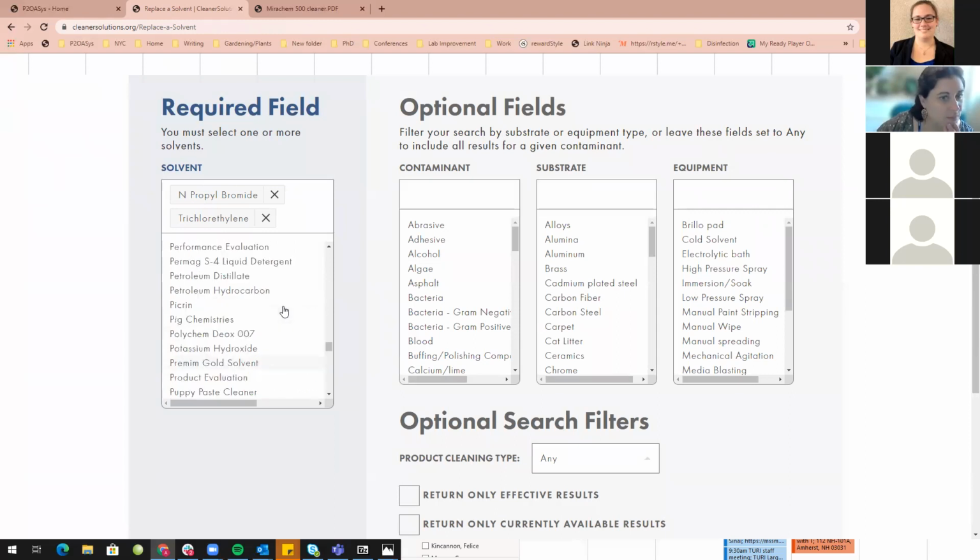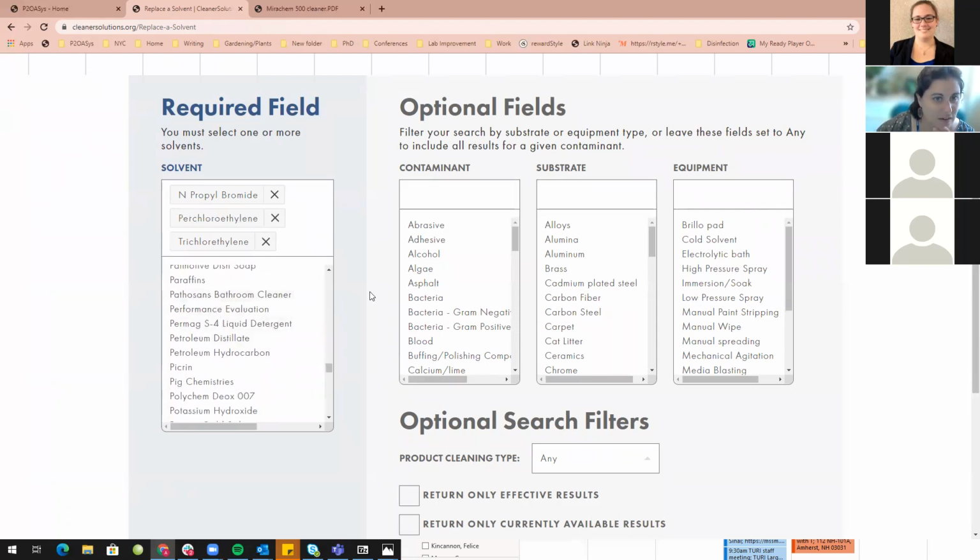Alicia, this is Mark. I know one company in Indiana that attempted to replace their vapor degreasing solvent, TCE, with a blend of solvents. One was 1,2-trans-dichloroethylene, and then there were two other VOC exempt solvents. They might have been HFCs. But what they found out was that they were not able to replace it, so they ended up going back to TCE.